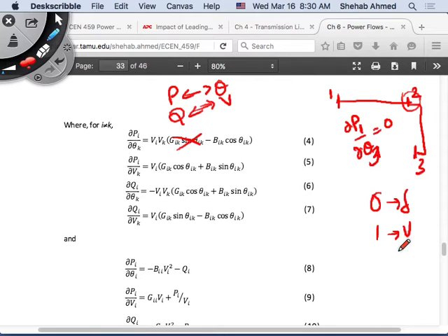But at the transmission level, the utility company needs to make sure that it's supplying as much of the power as it can to the consumer. So it wants to optimize or improve its efficiency as much as possible. So it will select transformers, cables, etc., such that the resistance is almost zero. Remember, in the transformer we would just put a series inductance. In the cables, we put a series inductance. We were ignoring the series resistance because it's small at the transmission level.